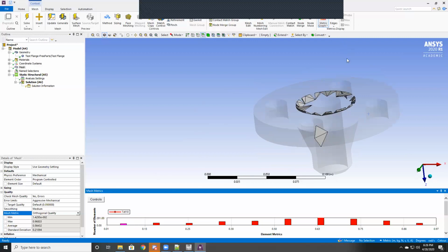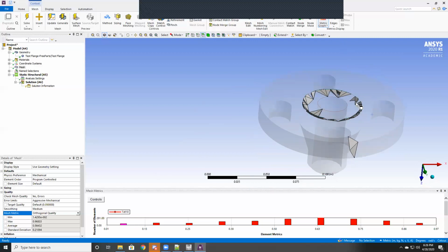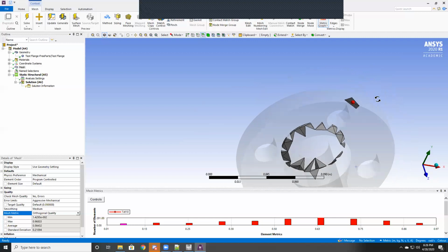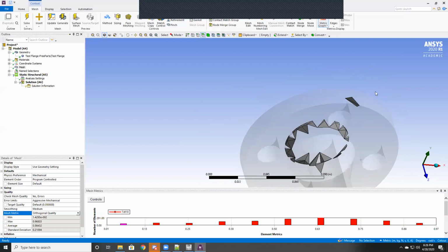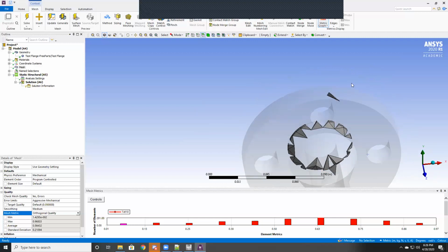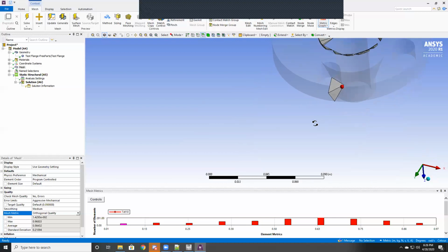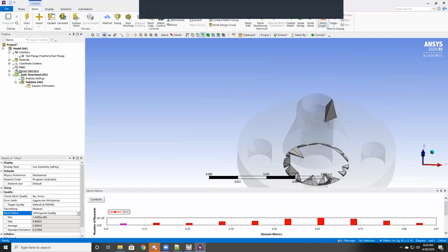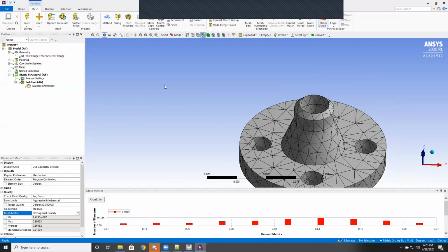However, our lowest quality are, again, in there, where they're very, very narrow on one face and very broad on another. Not very good. You can see another example here of this frankly dreadful tetrahedron that's just kind of shoved in there. So the first challenge is, how do you improve that quality and that skewness? There's a whole bunch of tools that Ansys gives you to improve the mesh, but you have to do almost all of it manually. One that's fairly straightforward for getting started is you can set a method.